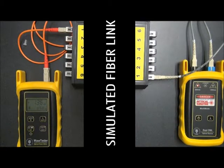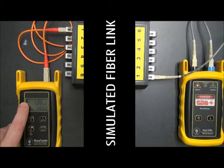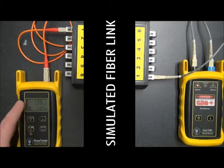In this case, we have a reading of 1.36 dB of loss. Now, this negative sign indicates loss. If there's no negative sign here, what this means is that there may be some issue with the test procedure, and you might have to do some investigating. However, since we have a negative sign here, we have a valid reading, 1.36 dB of loss. Now, whether this is a pass or fail remains to be seen until we download the test results into the software, but we'll do that at a later time.